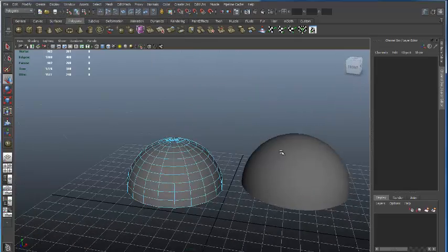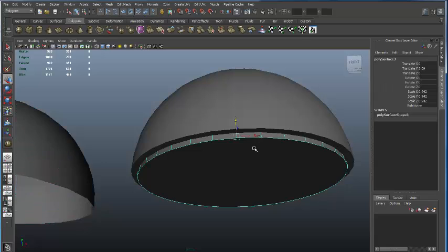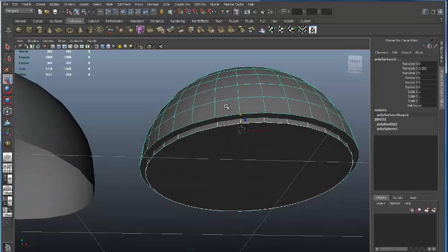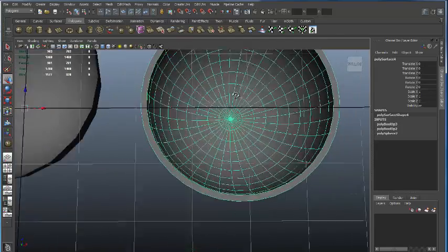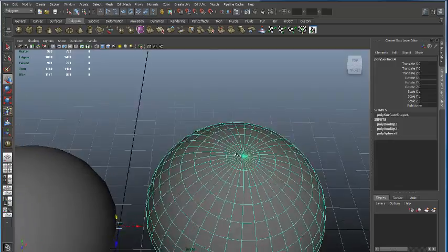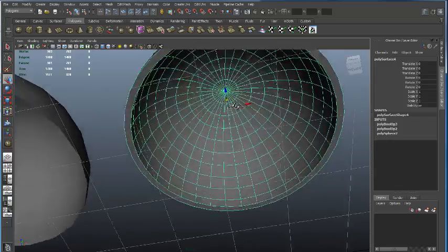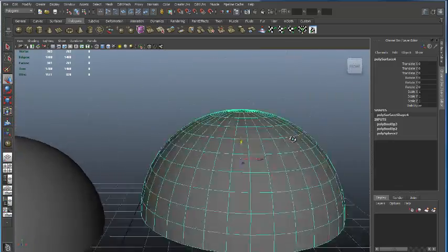Okay, it looks like it would just fall apart. So now by coming in here and taking this and this one, that's the object I'm going to keep, the object that's going to affect it: Mesh, Boolean, Difference. And now look at my rocket engine base. Okay, it has some thickness to it, it looks cool, it's nice and rounded.